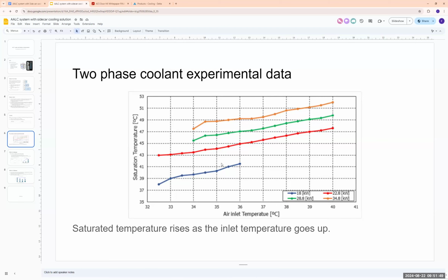But from the air side, if you are using 10 kilowatts with a delta T of the air of 10 Kelvin, it will be almost the same for the technology. There are no differences on the air side, because you have a heat exchanger, a pressure drop, and a flow rate, and the flow rate and pressure drop determine the fan and the efficiency of the system. So you will not have big differences, I think. So why would you want to use two-phase?